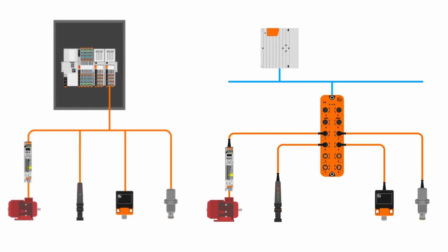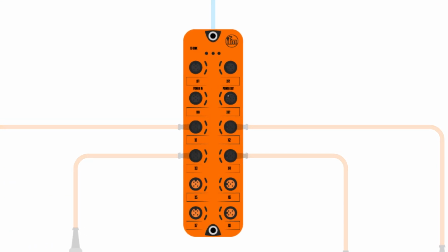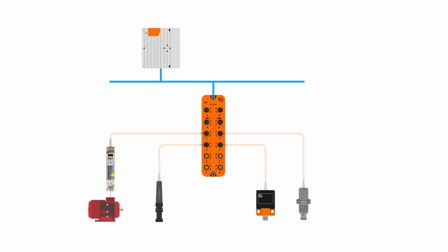As a component of an I/O system, the IO-Link master is installed either in the control cabinet or as remote I/O directly in the field. The IO-Link master can have several IO-Link ports or channels. An IO-Link device can be connected to each port, meaning IO-Link is a point-to-point communication and not a field bus. The IO-Link protocol allows an IO-Link port to be operated in one of 4 operating modes.